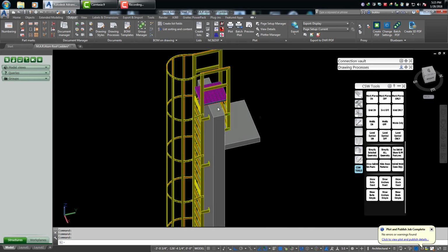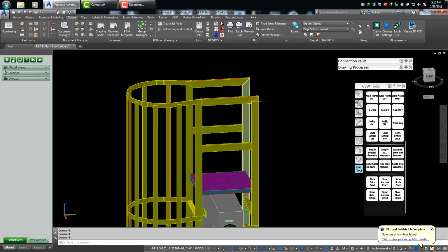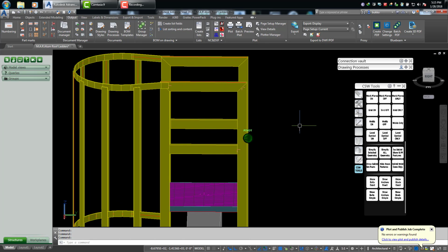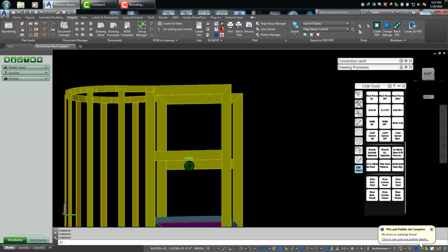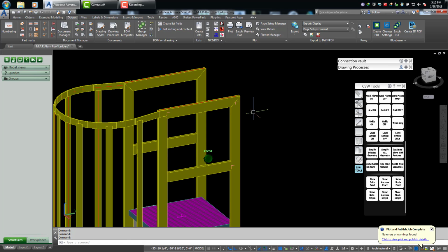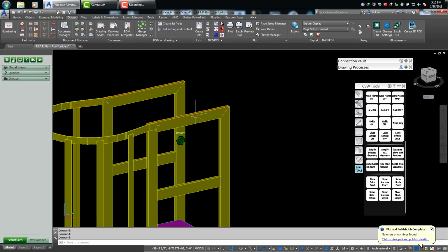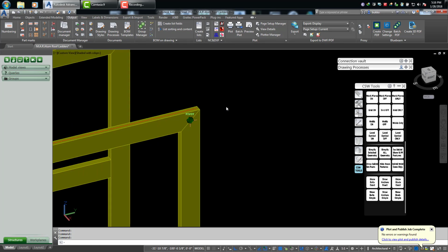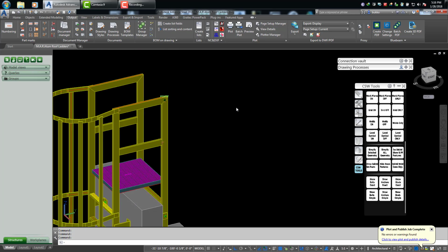Okay, so this is the over the parapet cage ladder style, and we don't bother doing any kind of radius top here. It looks better and it's a little more comfortable ergonomically, but as far as fabrication goes, it just requires more prep and setup. You've got to cut these pieces to the proper length. We have water jet capability and a plasma cam as well, but again, it's just something we don't elect to do. It'd be kind of difficult to bend these 1x3s the hard way anyway on any kind of rolling machine, so we just go straight across and miter the corners up top.